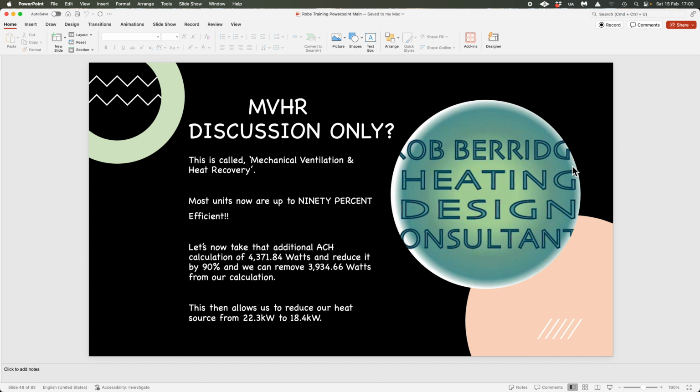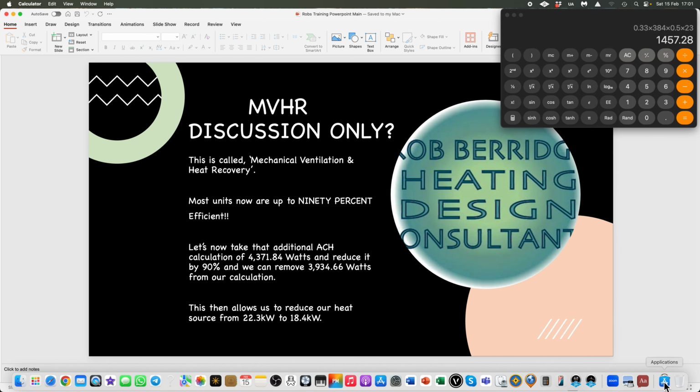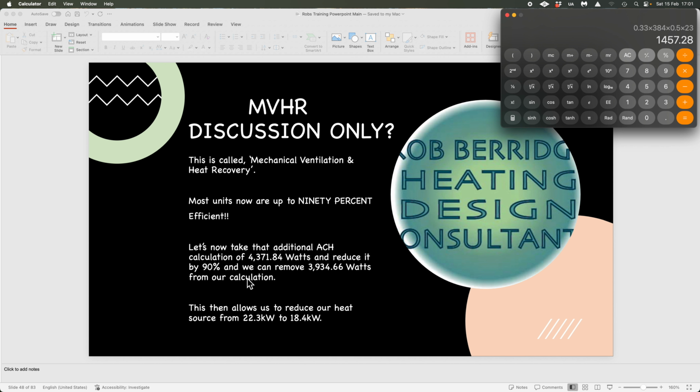And so if you can recover up to 90% of that, let's have a look and see what we've got. So if we had 4,371.84, as we had, and we reduce it by 90%, we can remove 3,934 watts, so 3.9 kilowatts, off of that whole equation there. But let's play around with this to see exactly what we've got.